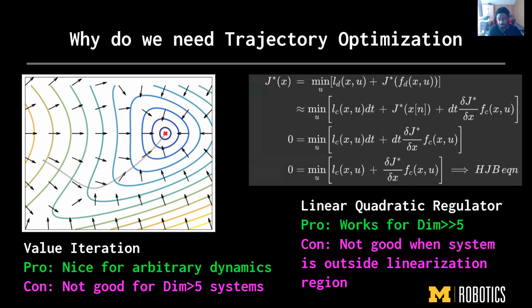And that's the drawback of LQR. We basically have to be linearizing all the time. The controller you end up with is mostly going to be pretty good in the linearization region. So if you linearize at some state X, your controller is going to be perfect for that state and surrounding regions. But as you go further from that state, your controller is going to be more and more terrible. So for each state you have to re-perform the linearization, and that might not be optimal for tasks that require a longer sequence of actions.